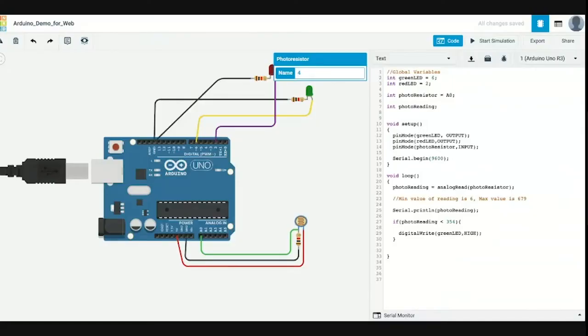And now we're just going to simply write another if statement. Usually an if statement comes with an else condition, and this is a prime example of using an else condition. But what I want to show you is that you can use if statements to create these thresholds for decision making. They're basically logic gates, but you can create more than 2. You could create 4 in this case if you wanted to have 4 LEDs all controlled by the same sensor.